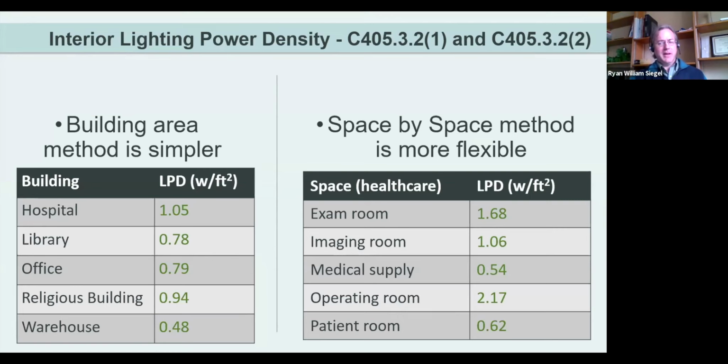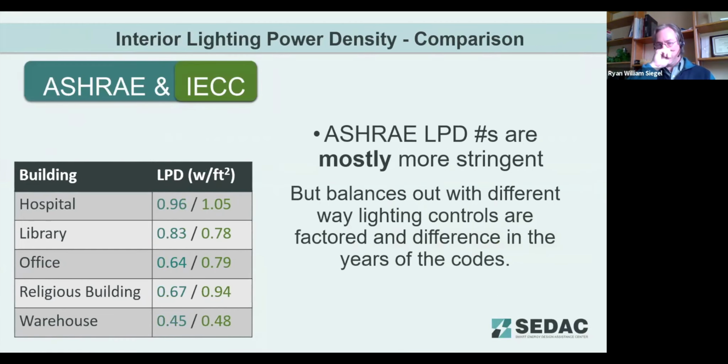And again, noting, earlier we had that example, we're getting somewhere in the 35, 40 foot candles with a quarter watt per square foot. A lot of times we can even see, even at 0.4 watts per square foot, easily being able to get 45 foot candles, which is generally acceptable for most purposes out there.